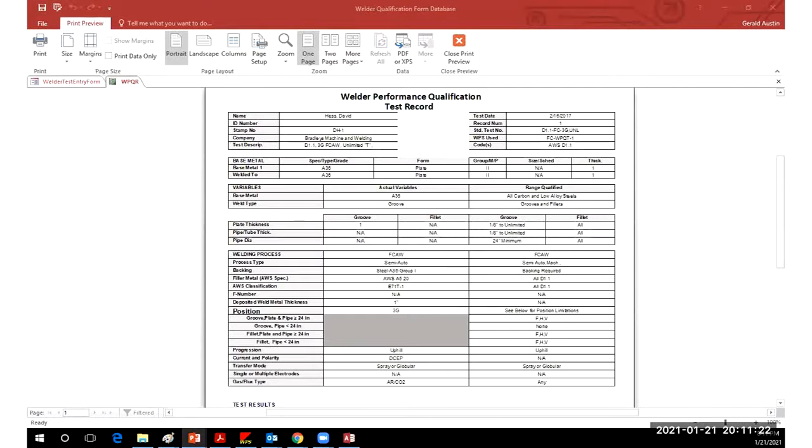I said, well, do you advertise your tent stakes as being built in accordance with any industry code or standard? No, we just got this drawing. Well, let me see the drawing. The drawing just says weld it there. By the time we get through it, that's when I refer to AWS B2.1. I said, well, if you would like to say that your welders are certified to something and you're not doing your manufacturing to a code, then B2.1 is a good way to go.